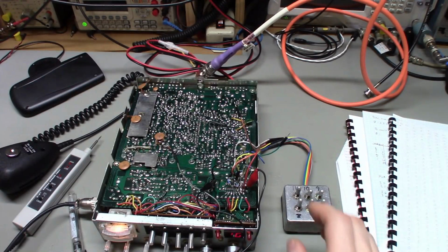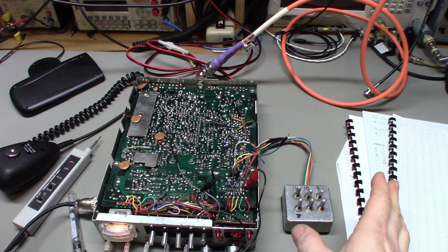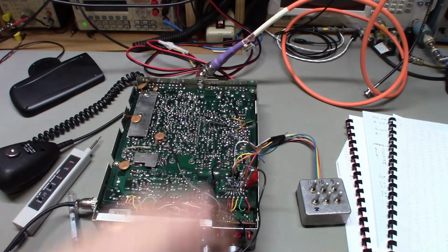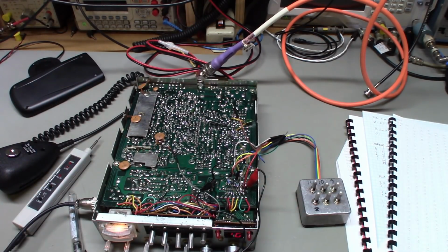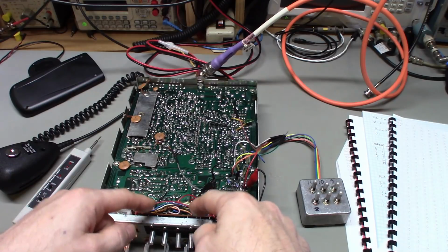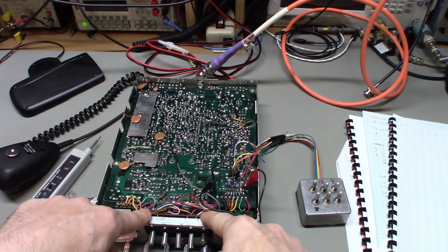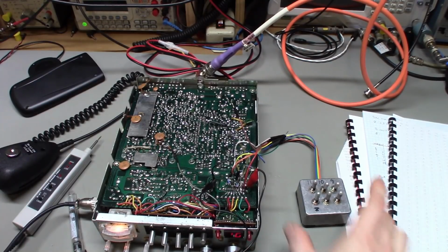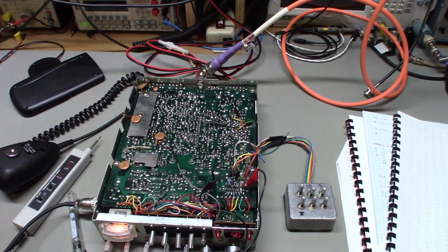Fifteen, 20 years down the road, either you don't want the channel modification anymore, or the next owner doesn't want them. The only thing you have to do to remove the channel modification is take the cover off, desolder the ribbon cable from the circuit board, reattach the cut traces, and the modification's gone. It takes literally like 2 minutes to unmodify, whereas if you do something with these switches, it can take hours to undo the modification. So save me a headache. Use external boxes.